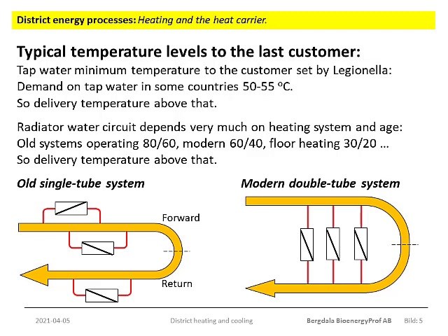To guarantee that, the production unit will have to pump out district heating water that is significantly warmer. In northern Scandinavia, the output temperatures from district heating plants would be some 120, even up to 130 degrees during winter. But then the high temperature increases the heat losses, so you always want to pump out water at the lowest possible temperature. The limit is set by what arrives at the last customer. So during summers the output temperatures are significantly lower.